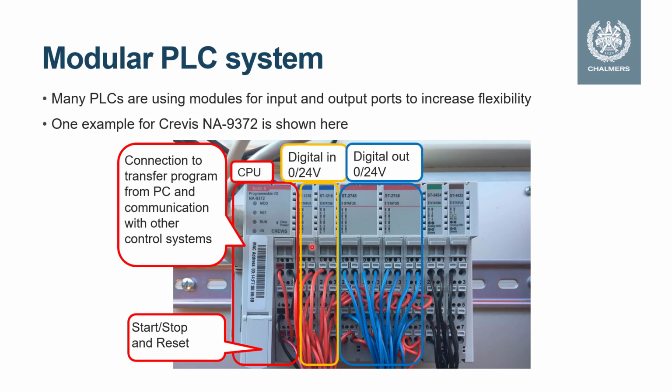Here I have my digital output modules. They are also connected to 8 signals, 0 to 7. They look twice as big, but that's because they need a reference signal as well. I have 2 output modules, 8 signals in each, which means that I can send out signals to 16 different actuators or lamps or something else that I would like to control.